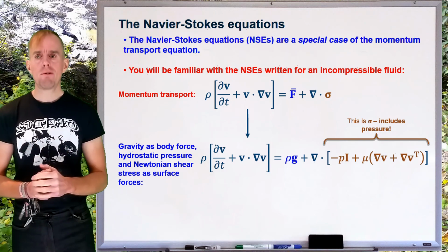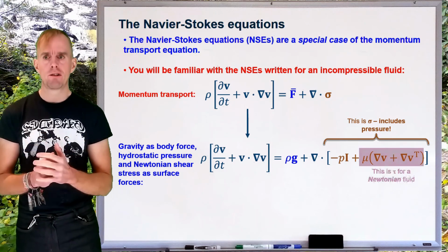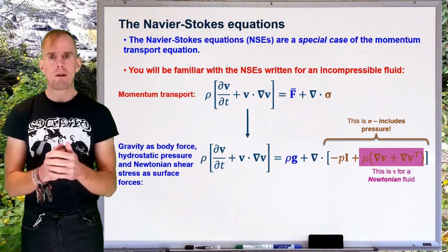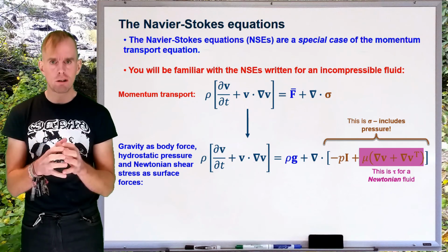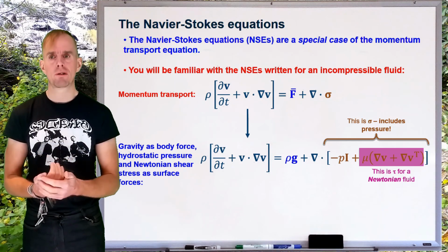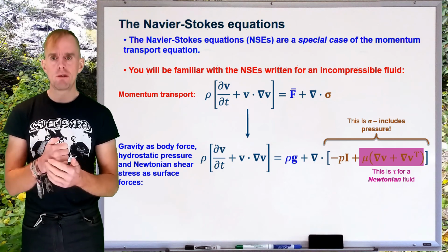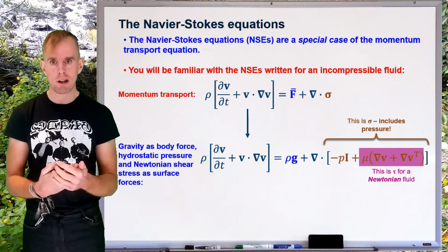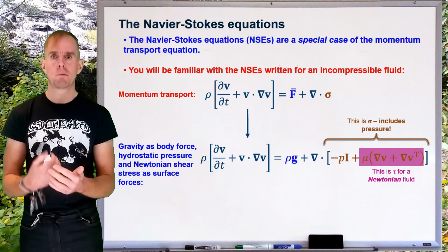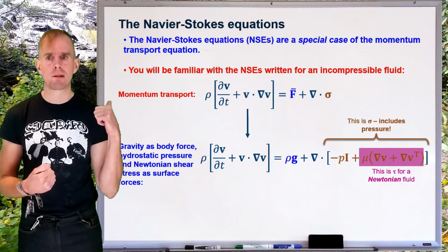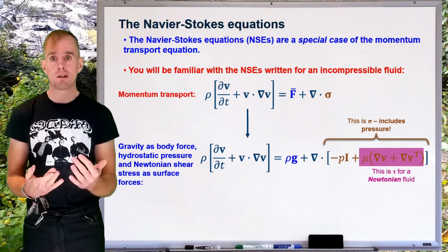If we think of the other terms in this equation, we've got mu times a shear rate. The shear rate I've written in a certain way, which I'll explain in a minute, but when we think of Newton's law of viscosity, tau equals mu du by dx. Du by dx is effectively a velocity gradient, which is my shear rate, and mu is the material property of viscosity that relates to the fluid. And so I've got that exact same statement here, just in 3 dimensions.